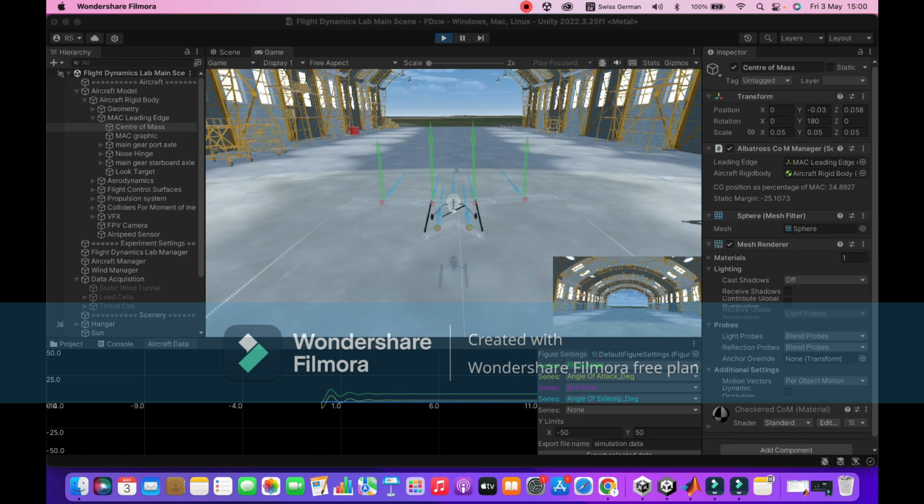The aircraft pitching moment response is evaluated by changing the center of mass location vertically. A lower center of mass location tends to increase static stability because it creates a pendulum effect where the weight of the aircraft is lower than the area where lift is generated. A lower position of the center of mass increases the damping of oscillations, and that can be seen from the simulation.